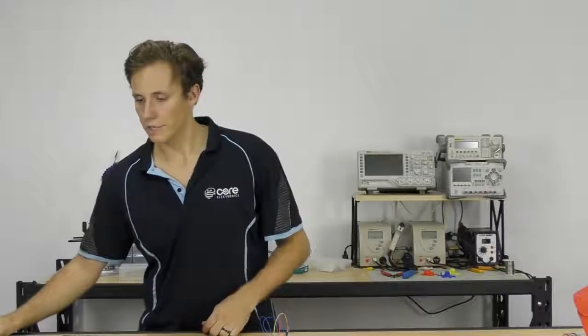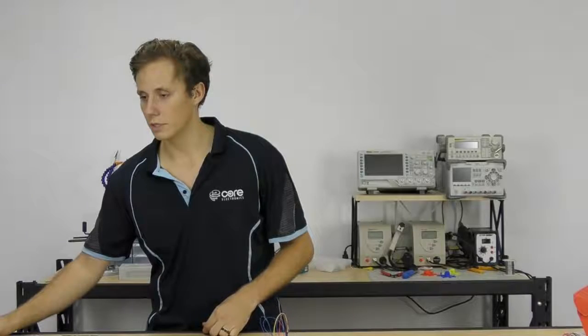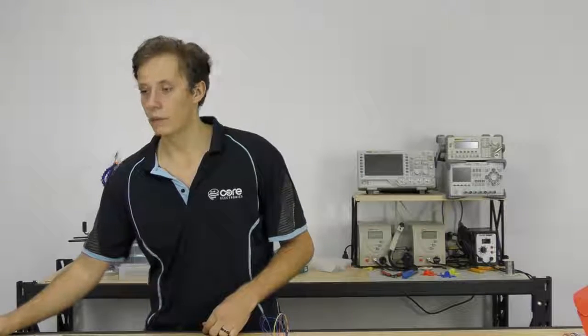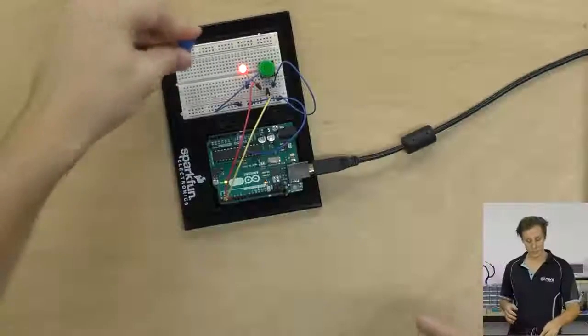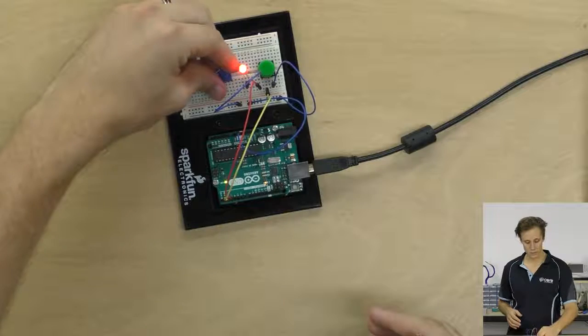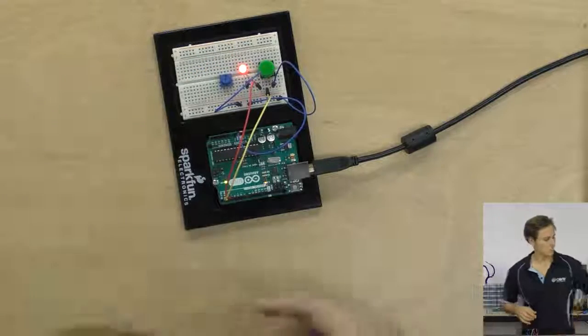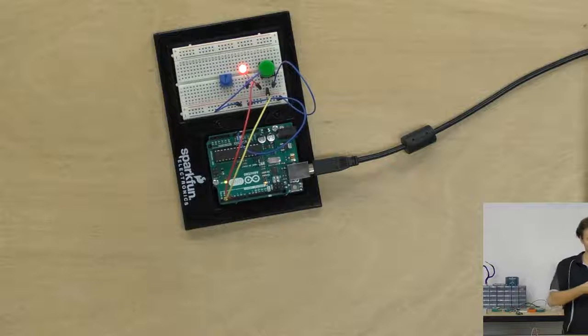So to connect up our potentiometer, there's a circuit diagram example in the section resources. And you can see here how we've got that wired up. So we've kept the LED and the button in the circuit. We're going to take those 3 pins. These need to be isolated from each other. So we're going to connect it in this direction to our breadboard. Take some of our trusty jumper wires